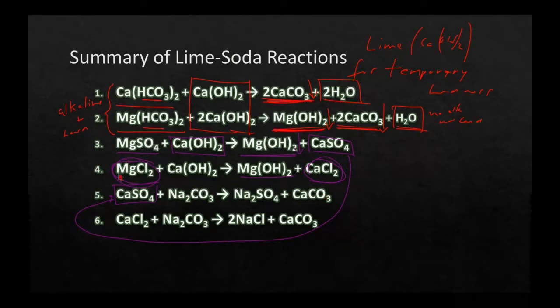You know, all we've done is a double replacement reaction. All we've done is swap the calcium for magnesium. So it's basically we've done nothing, right? We have not removed the hardness at all. All we've done is change it from its magnesium form to its calcium form.